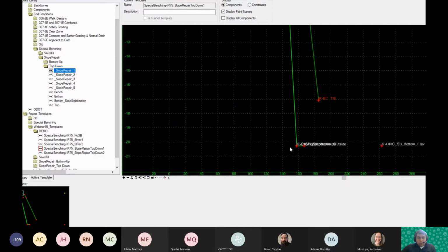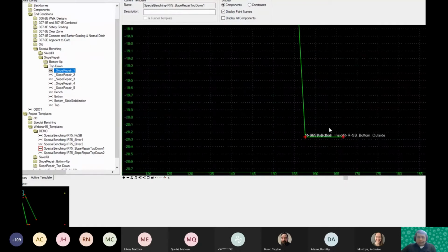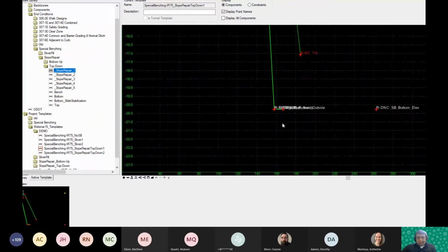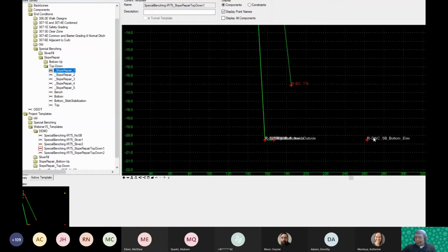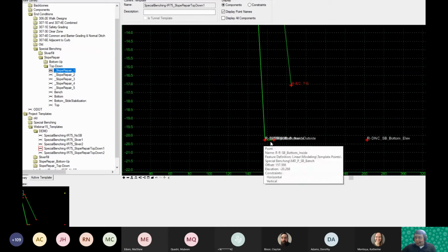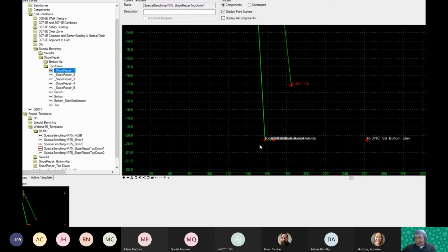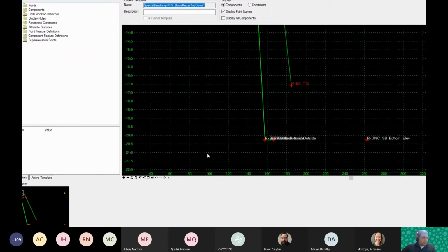So when you initially throw this into your corridor, you get something that looks decent. I mean, if you tell the elevation to go to elevation 1,000, and your project is down at, I don't know, elevation 600, 700, that's going to look pretty stupid when that elevation goes way above your roadway. So this is purely just giving it a starting point.